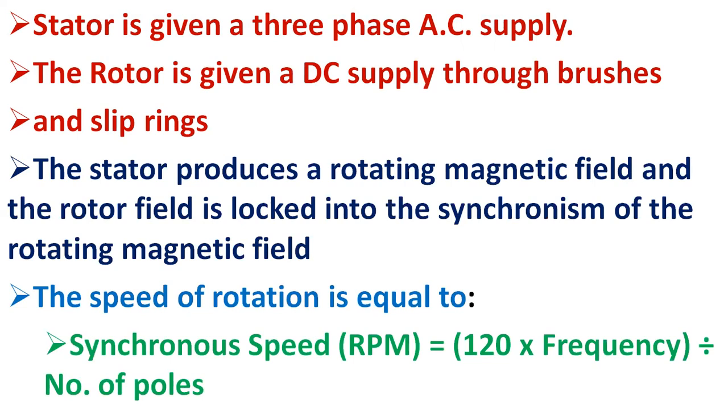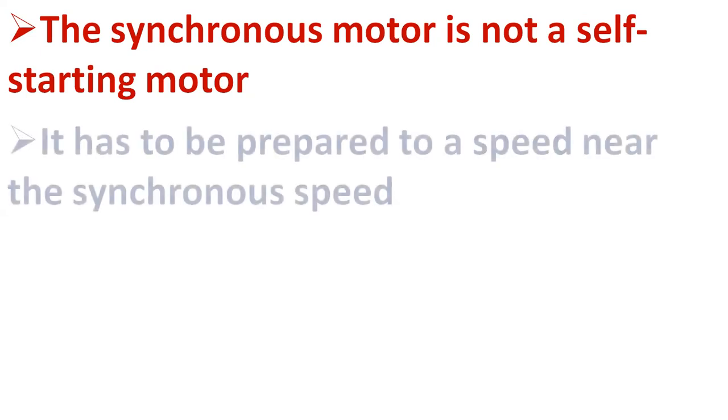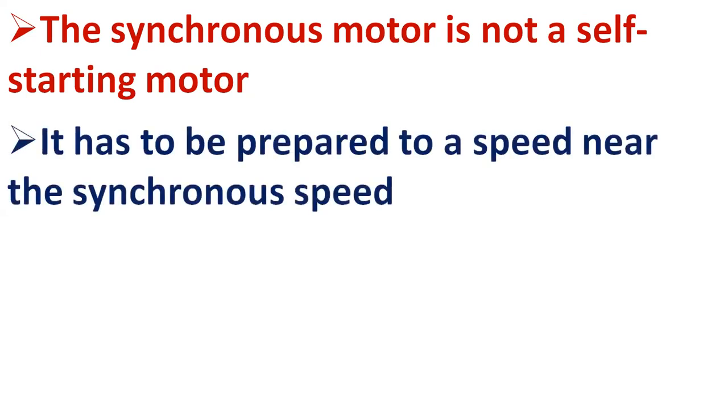The synchronous motor is not a self-starting motor. It has to be brought up to a speed near the synchronous speed so that the rotor gets locked with the stator's rotating magnetic field. At one point of time in the history of technology, this motor was quite popular.